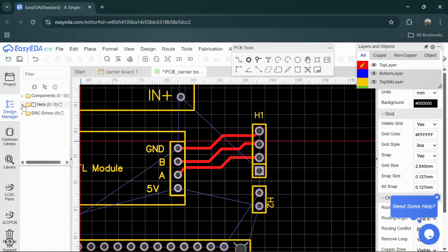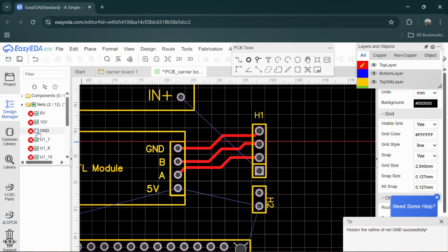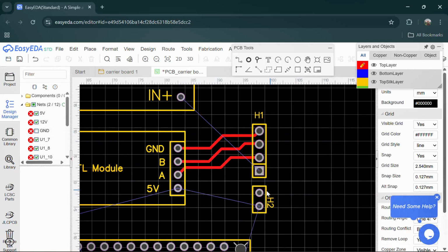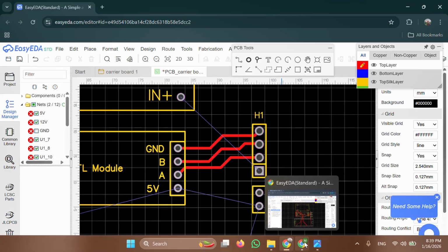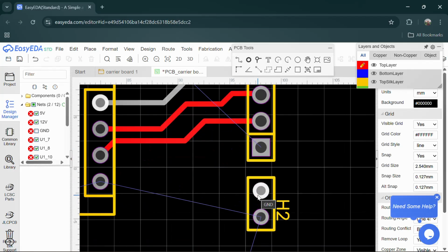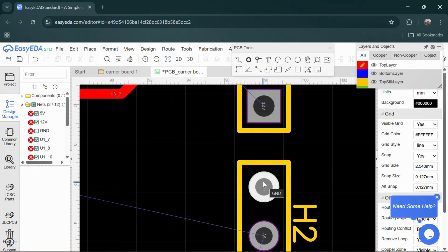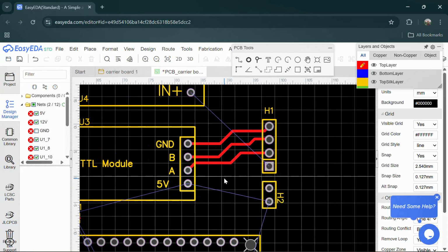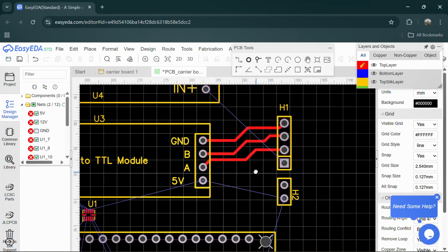Click on nets, as these blue pins are nets, and unselect the ground button. This is because we will make our whole PCB layout ground at top and at bottom plate. We will do it later. For understanding, for now we will not connect the ground of all components, but we will just connect it at the end of our PCB when it is built.